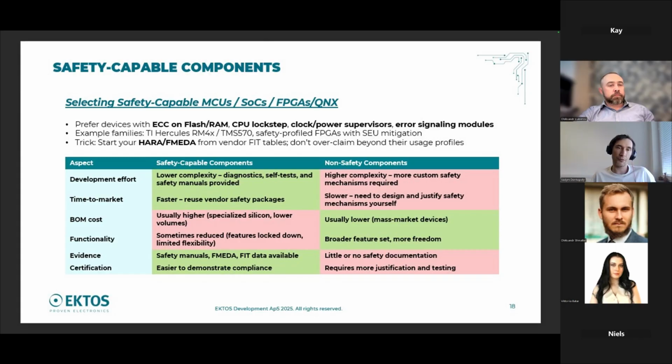If you want to make a safe product, look first into components which can provide safety features, and when they claim that they can give you this ability, it improves or accelerates the process of certification. These components cannot replace all the certification. If you put in all components which are safety capable, it does not mean that your system is safe enough. Anyway, all the process should be done, but some of the steps could be eliminated or reduced.